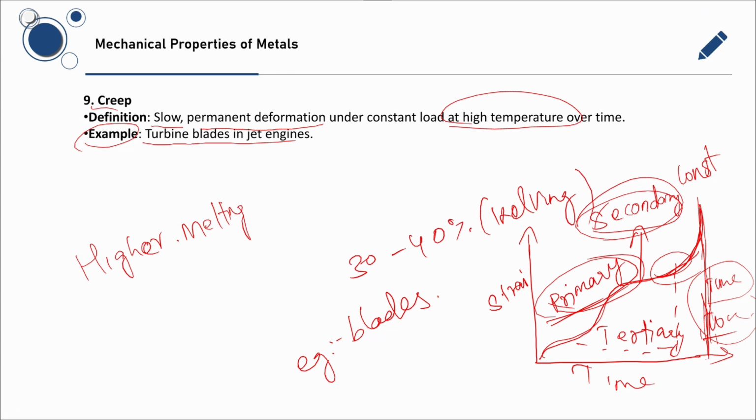So a higher temperature or stress makes the curve steeper and shortens the time to rupture. For hot parts, we pick creep resistant alloys and design so service stays in the steady state creep with a low rate, well before tertiary damage begins. So this is the creep curve.